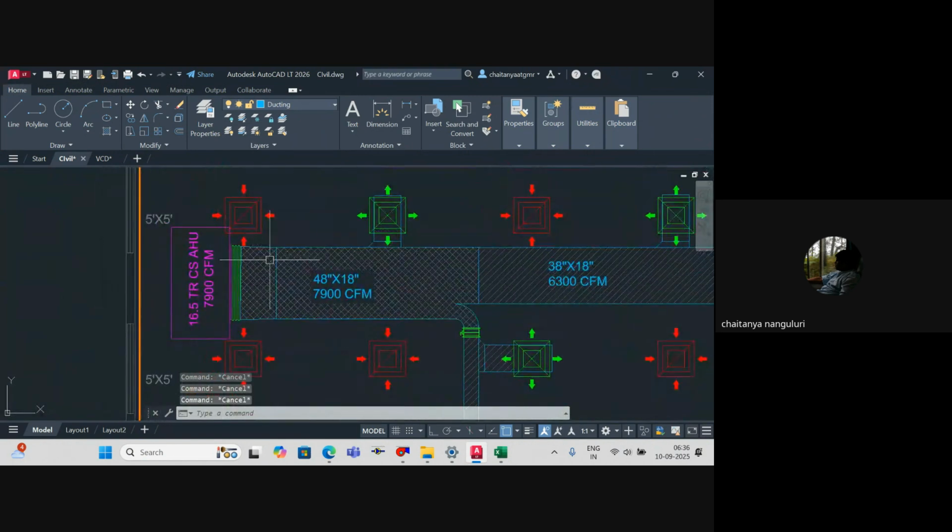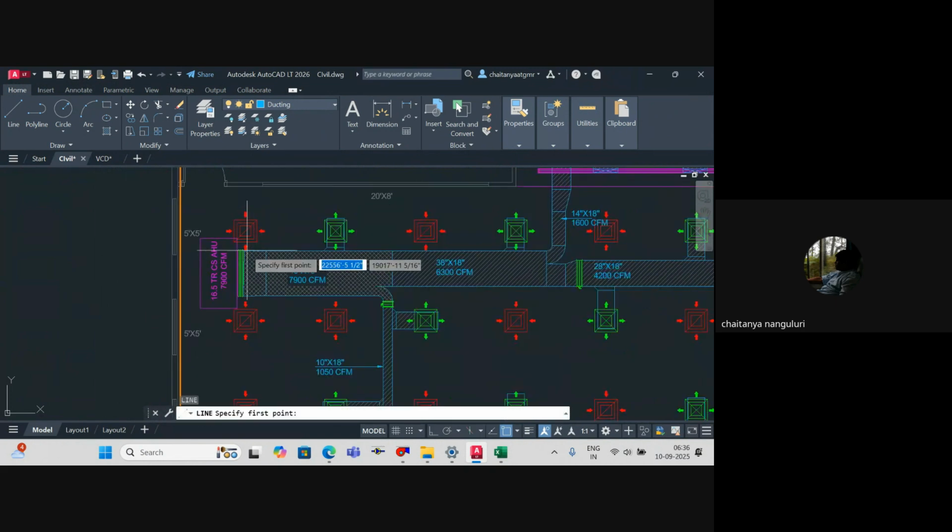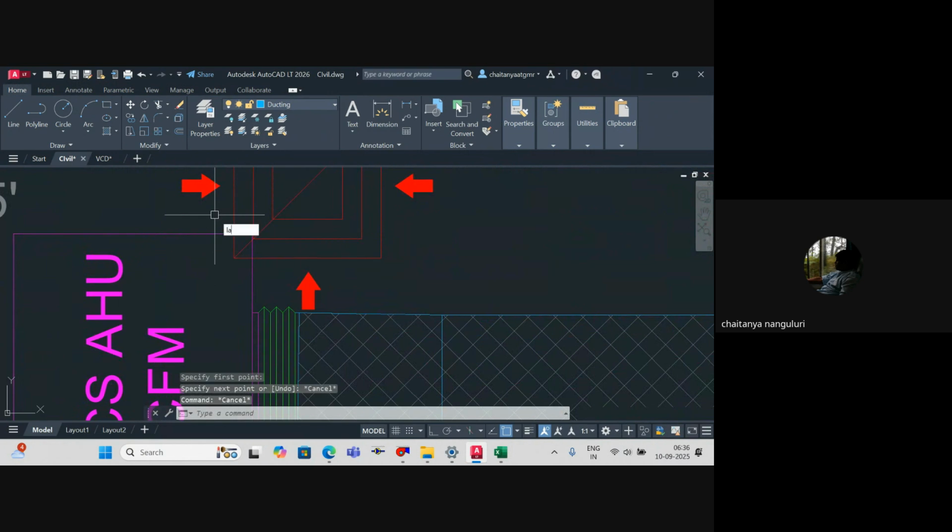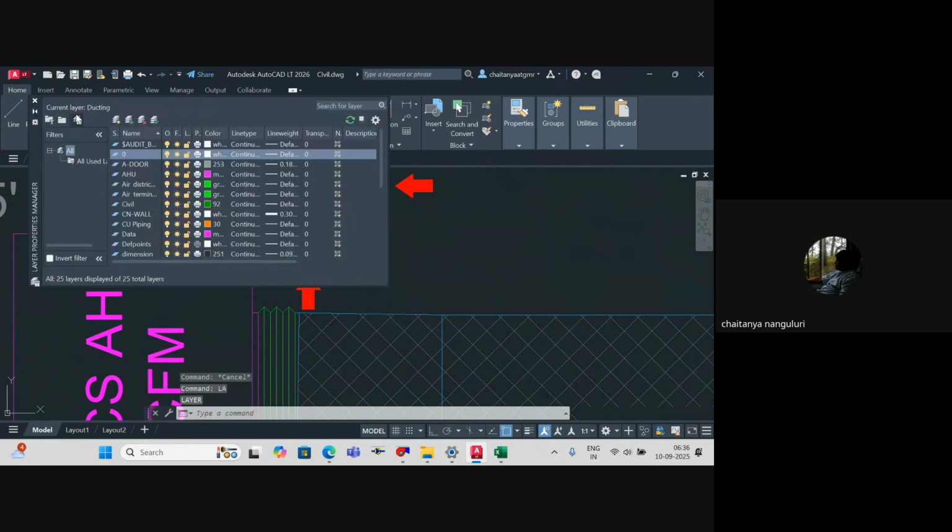So coming to the drain diameters, theoretically they say even up to 10 tons, your 25 dia is fine. Generally, what we do is up to 5.5 tons we go for 25. More than that, you go for 32, it should be fine. Understand? For example, in this case, I'll directly go for 32 dia. 32 or 50 is more than adequate for any project. Understood?